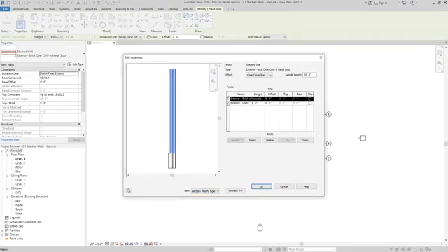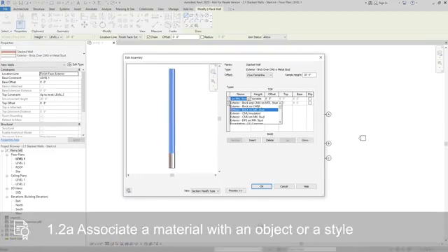By default, the stacked wall has two different types loaded in, and it's going to start off by giving us a base height for number 2 in our layers here. You can see as I select the different options, it's going to highlight which layer is which. For this project, we're going to go ahead and set the brick on metal stud as our base layer, and we'll set our EIFS on metal stud as our top layer.